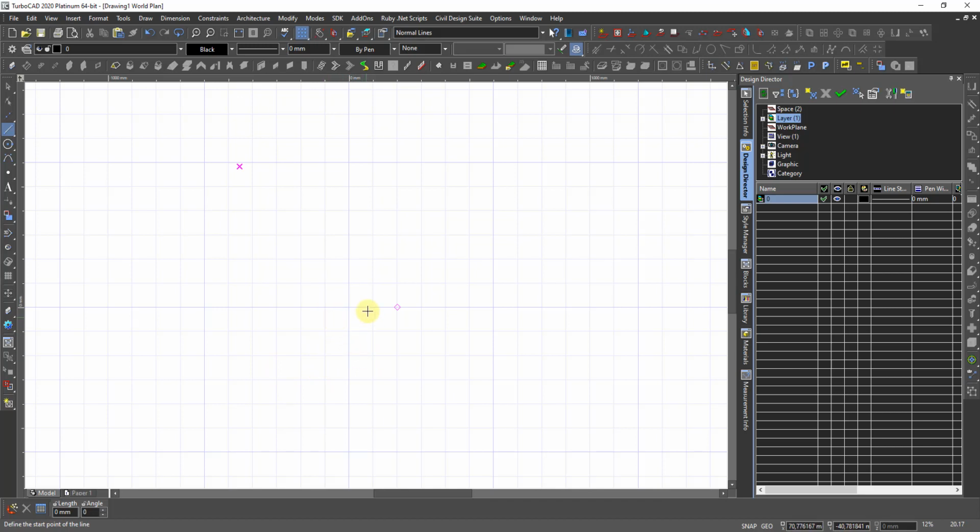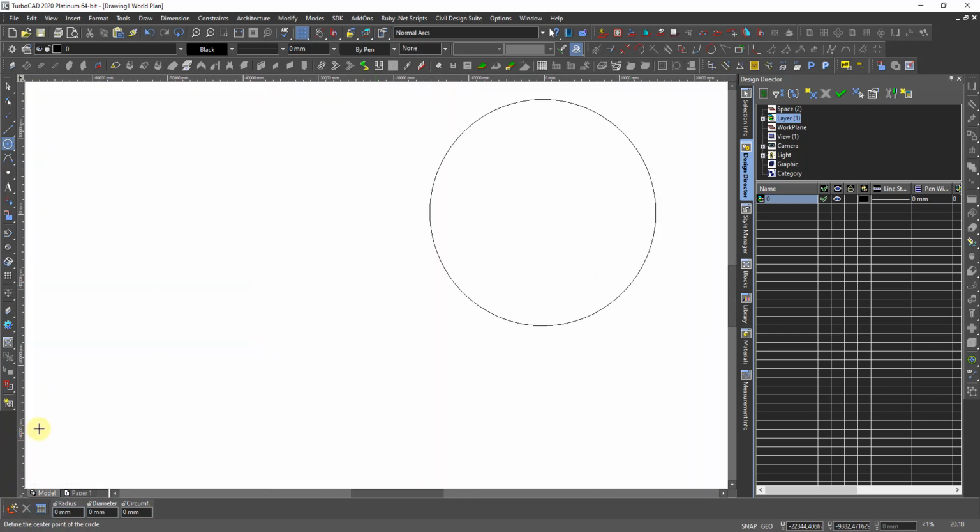I also many times put into my template a big circle. Then I go here to the circle tool, to place it someplace, and I say it should be 15 meter. That means it should be 15,000. Not diameter, that's a little bit too quick. I say over there, 0.5, 15, 1, 2, 3, enter. Then I have a big circle.